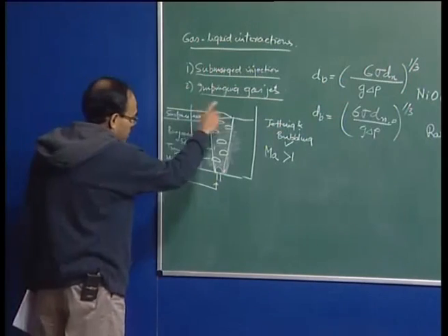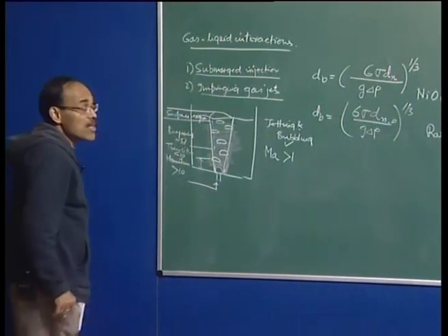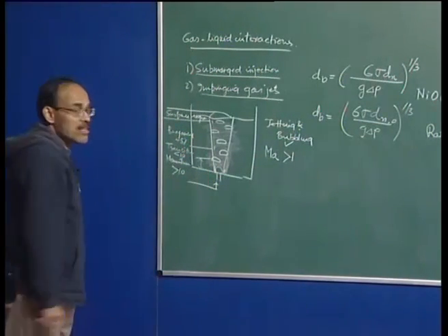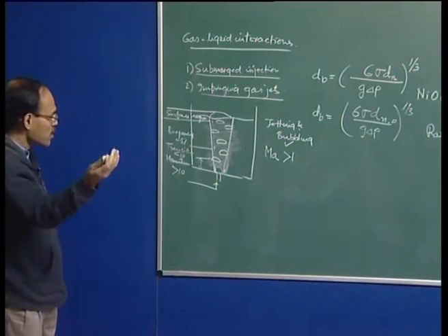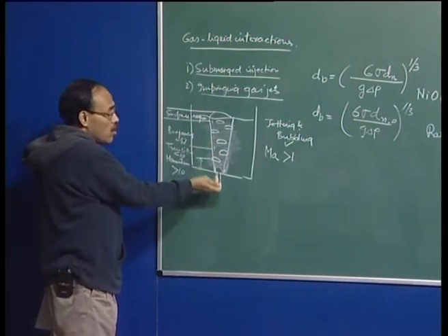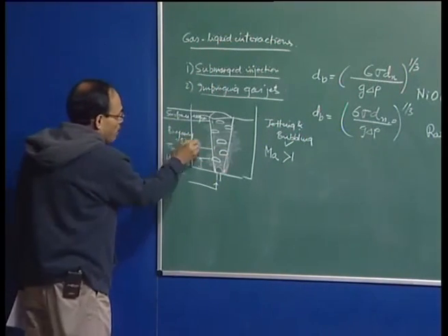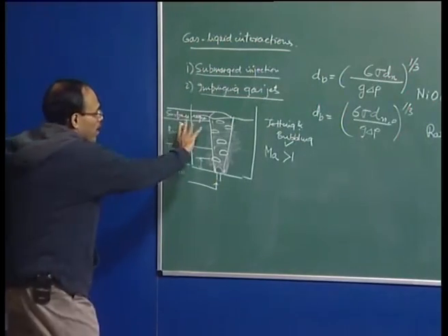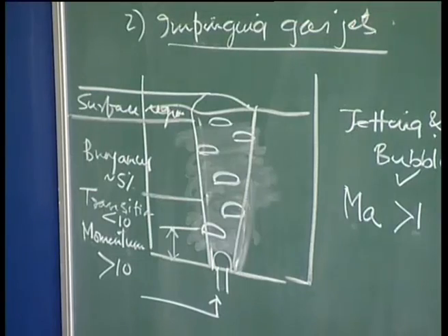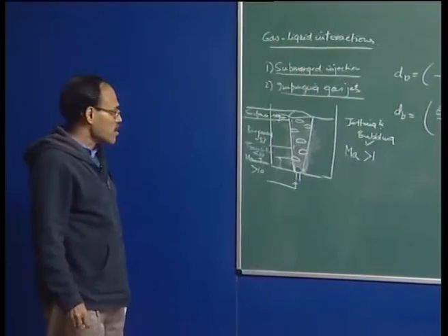To know the characteristics, a large part of this system is buoyancy. Therefore, the Mach number is much less than 1, and the free stream velocity is much less than 1. I will discuss this later, but the gas is injected, as I have mentioned, either through a nozzle, a tuyere, or a plug. And when the buoyancy region occupies the major part, at low flow rate when the Mach number is much less than 1, we can say that these systems are basically buoyancy driven systems.